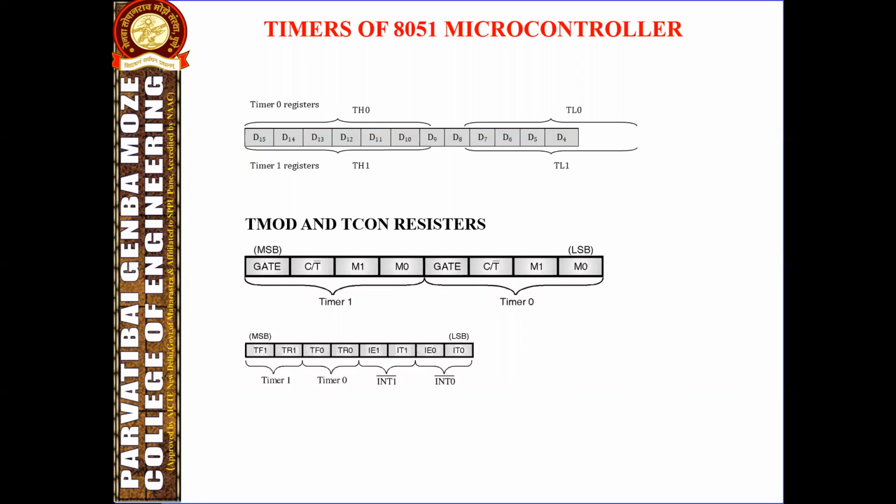There is no restriction on the duty cycle of the external input signal, but it should be held high at least for one machine cycle, to ensure that the input is sampled at least once before it changes.